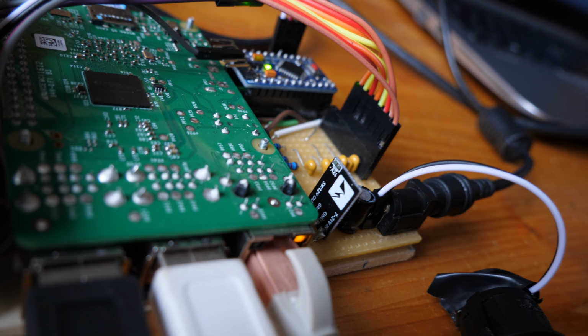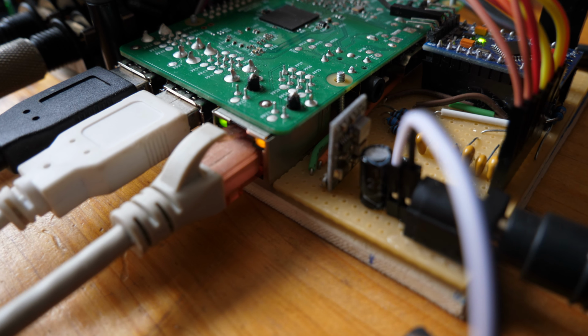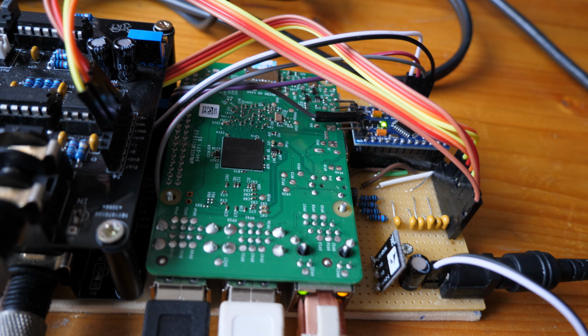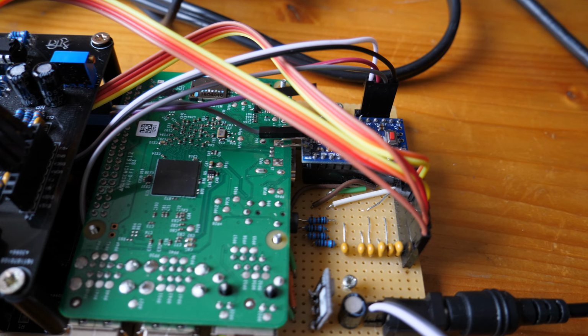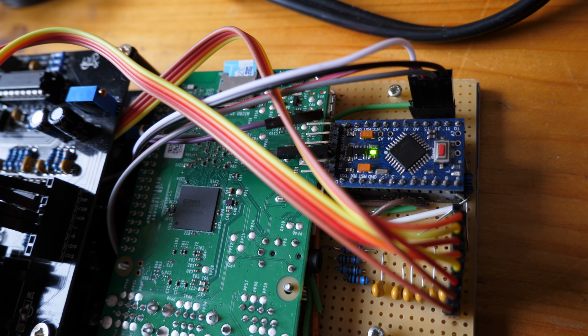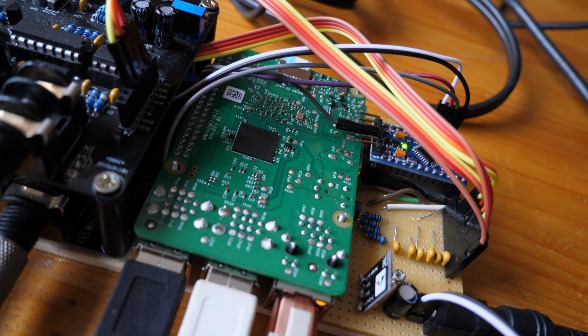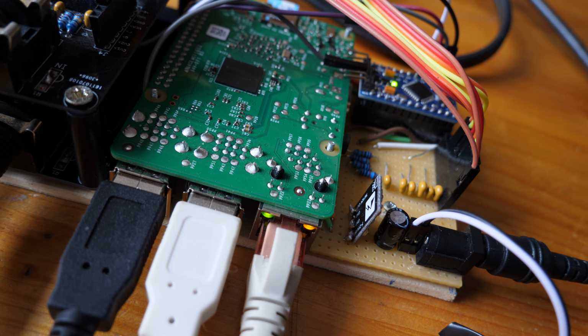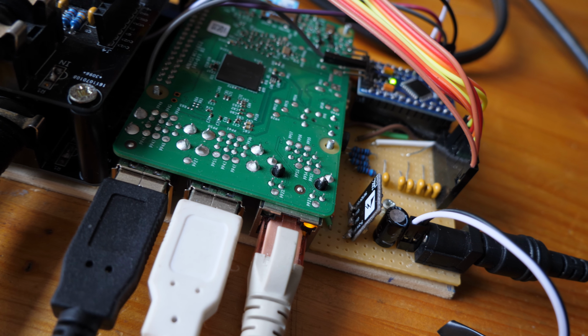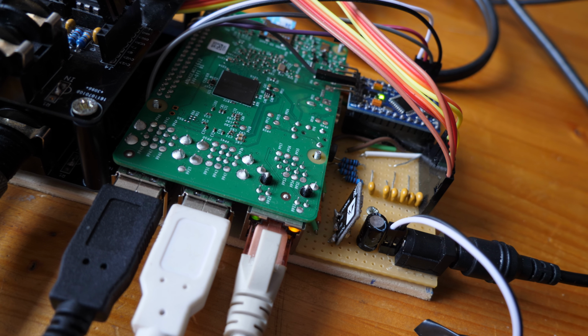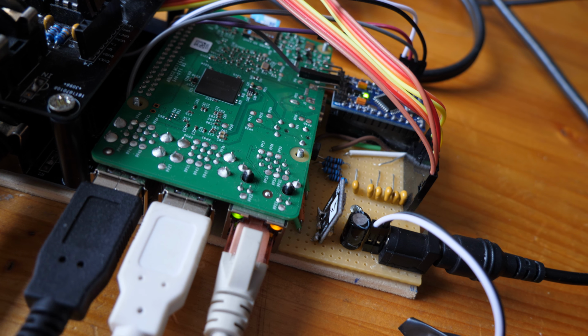I installed a nice power regulator, 12 volts to 5 volts for the Raspberry Pi. The Arduino is now on 5 volts because the boards needed 5 volts, and I just disconnected the return transmission signal because that would hurt the Raspberry Pi. But now the Raspberry Pi is sending serial data at 3.3 volts, and the Arduino is getting it no problem because I think it understands everything above 2.5 volts, so it should be fine.